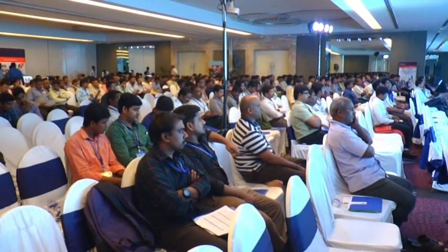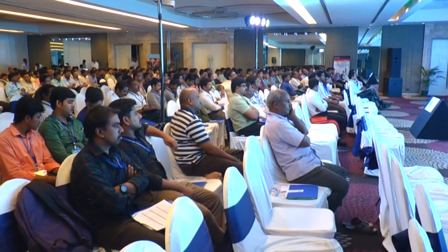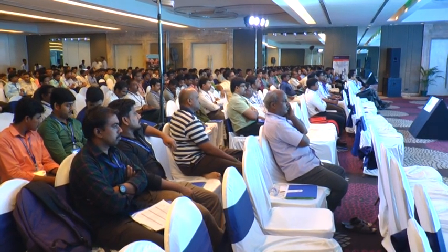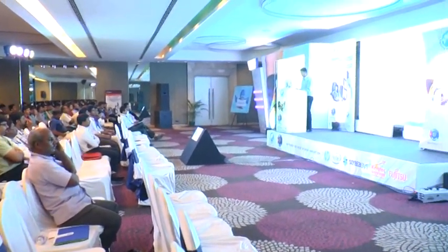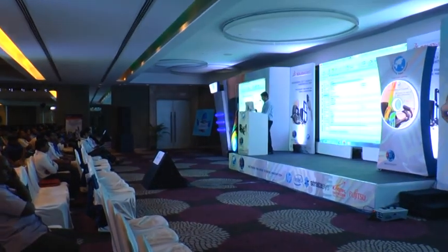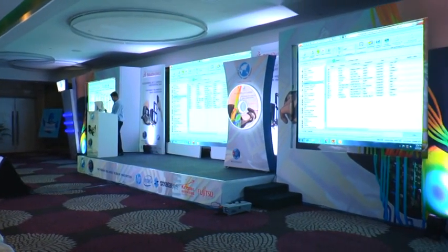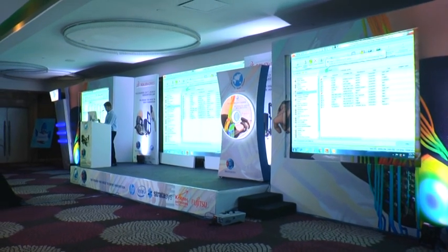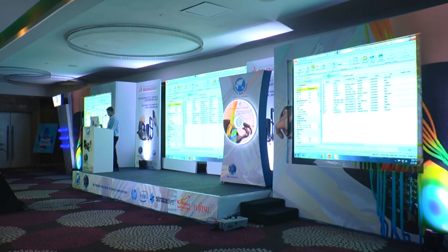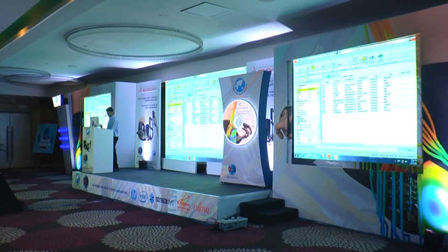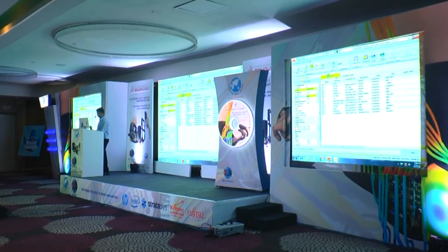So I have the connectors. I'm assigning some manufacturer parts. I'm typing some basic reference file name. Here I'm choosing Legrand. In the filter option, I'm going to choose the class type, whether it is base or auxiliary.